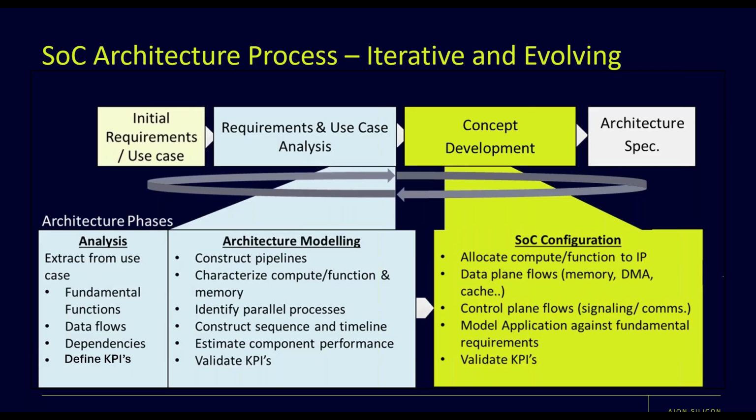There's then a lot of engineering that goes on to develop that into a first cut of the architecture. There are usually multiple candidates. We will explore different IP options, different processing options in order to deliver the various workloads in the software. This is where our partnerships with our IP providers really is important. We need to be able to get either benchmark data or find ways to exercise some representative software from which we can extract some data about the performance of the cores that we're potentially going to use that's relevant to our specific workload.